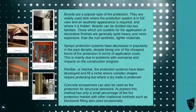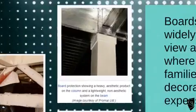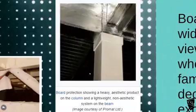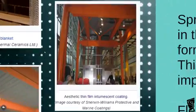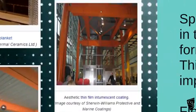And then there's the concrete. So a bit of a concrete here. If I just come and have a little look, can I get that picture up? So there's the boards, and they're just fixed on, probably on a timber frame inside. It's even got the beginnings of a cornice up here. And this one is just painted with intumescent paint, so you can see it's hardly changed the look of the steel at all. So that's intumescent paint.